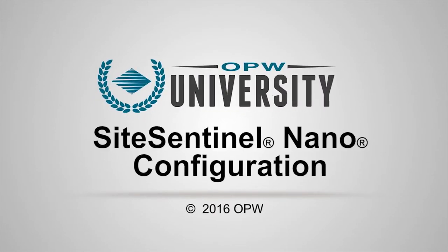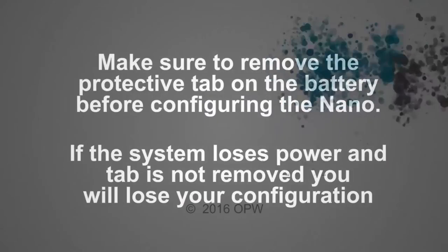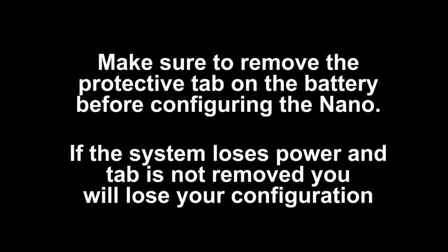Site Sentinel Nano Configuration. Make sure to remove the protective tab on the battery before configuring the Nano. If the system loses power and the tab is not removed, you will lose your configuration.